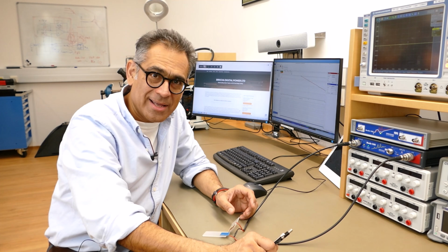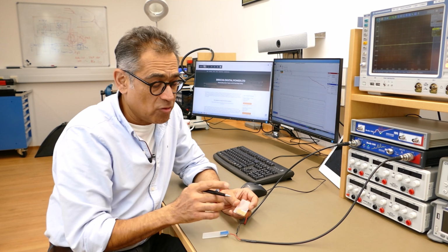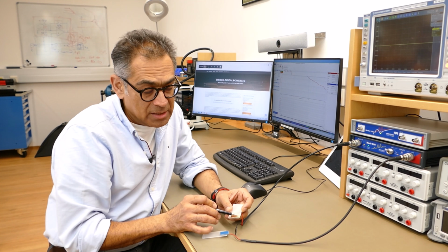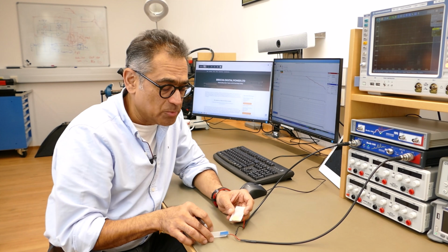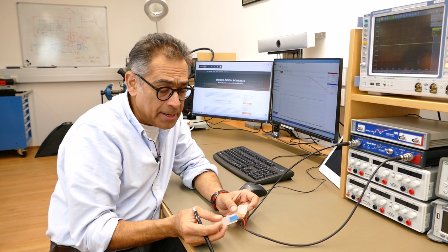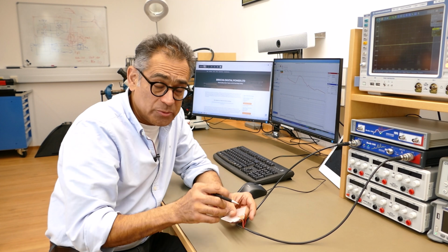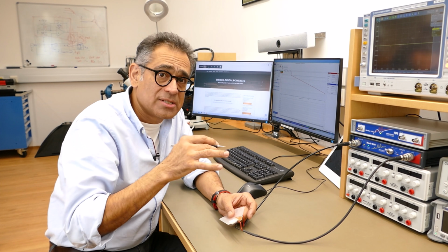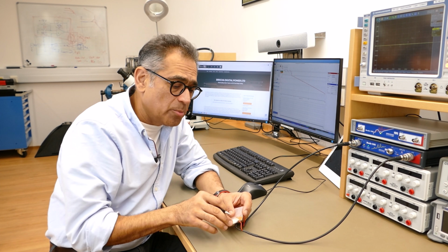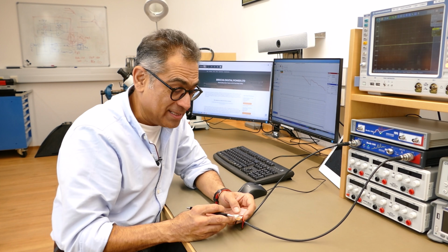So I'm here in my lab setup. I've got two little bits of PCB. This is just FR4 material. I've got one here which is 2 centimeter by 2 centimeter. It's a little bit smaller actually. And then I've got another one here. And of course when I put these two on top of each other, I will get exactly what we described. I will get two parallel plates, 2 centimeter by 2 centimeter each, separated by 1.6 millimeters of FR4 insulating material.